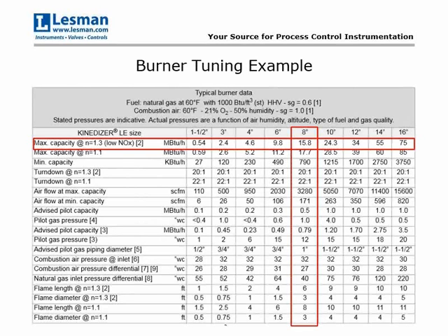If we look at this chart, we also see some other crucial information that will help us set up the burner. We see that we have a minimum capacity. It gives us our air flows at maximum and minimum capacity. It tells us what the pilot capacity and pressure should be, so that'll help us with adjusting the pilot. And then it also gives us our pressure differential requirements for the combustion air and for the fuel.